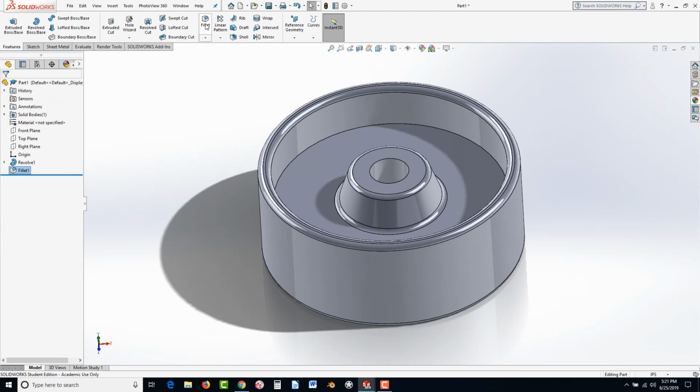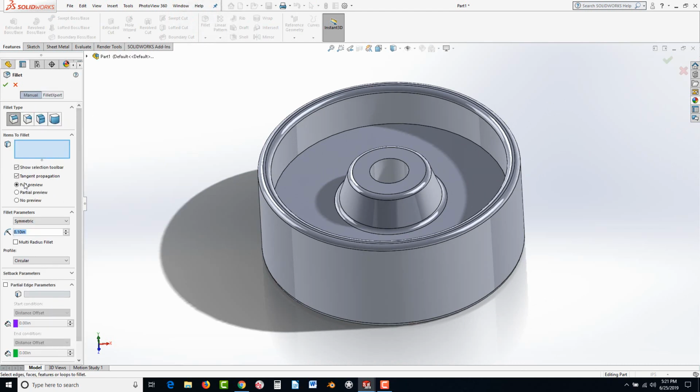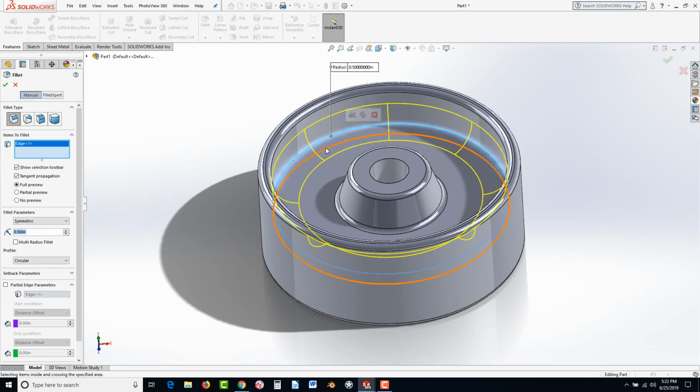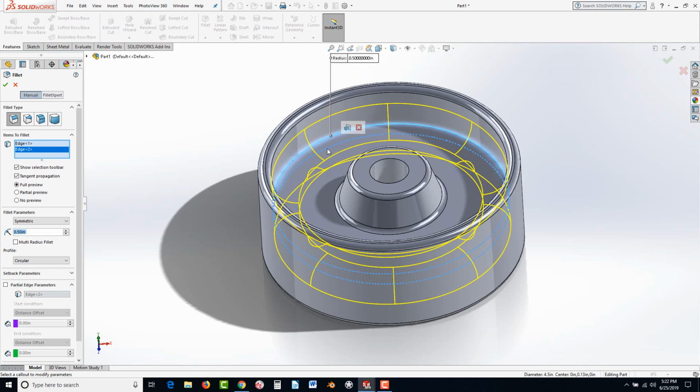Let's add a different sized radius. Go to Fillet, and now set the radius to 0.5, and select this edge here, and use the Xray capabilities to find that edge underneath it, and click on that so we don't have to rotate again. Hit the green check.